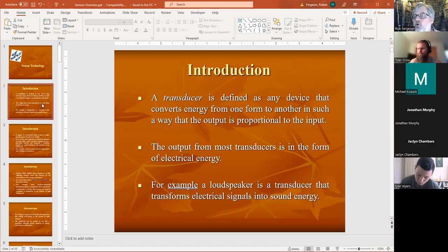in a simple transformation. For instance, I might have a temperature, and I want to convert that temperature into something that's readable by a small computer. And so I would convert a temperature into a small voltage, say between 0 and 10 volts, or a tiny microvoltage in the case of a thermocouple. So a transducer is simply something that converts something from one energy to another.